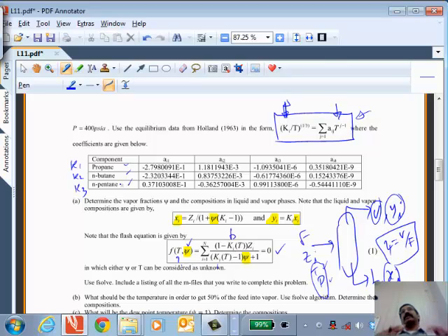Okay, I'm starting with a liquid, I'm adding heat. First propane starts boiling, and then butane, and then pentane. Now the first temperature at which the propane begins to boil is called the bubble point temperature. Okay, and that's a very important parameter. So we want to be able to calculate what a bubble point temperature is. Okay, the similar concept exists for bubble point pressure as well.